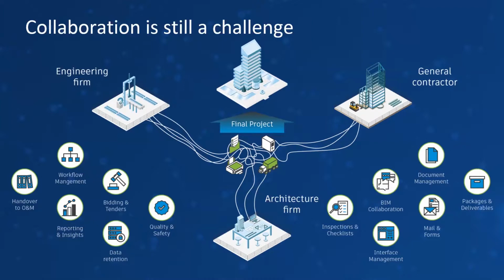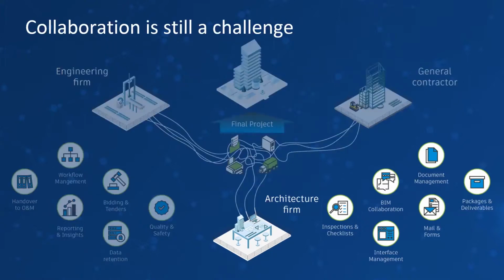But with something like BIM 360 Design, it connects the teams directly from within their BIM authoring tool. So directly from within Revit, you can sync changes, and it will sync those changes up to the cloud, and then the person at the other end, or even the team of people, can pull down all of those changes into their Revit model using BIM 360 Design.